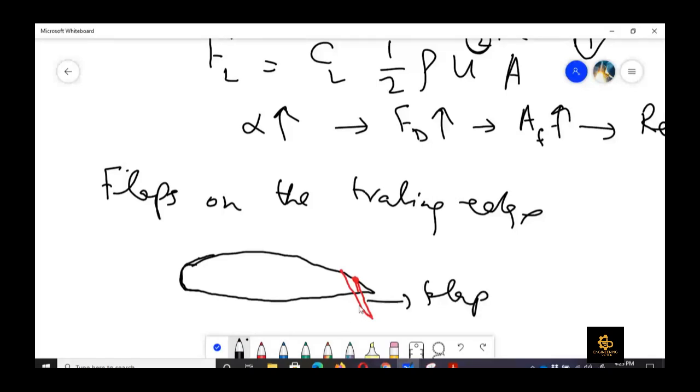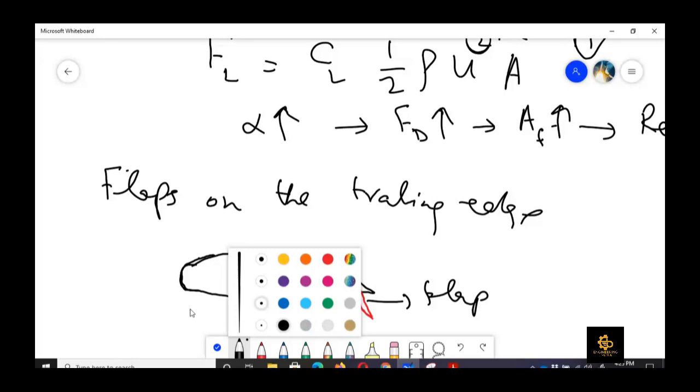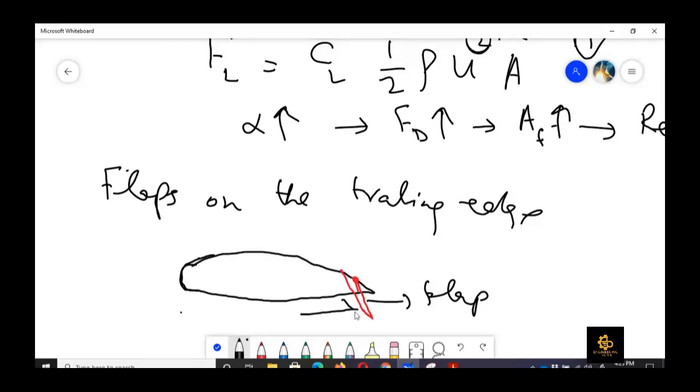When the flow is coming here, there would be higher pressure here as compared to this portion, so it would have higher lift. So it would increase CL. But the second consequence, because it is perpendicular to the flow, is that CD would also increase a little bit, depending on this frontal area, right? So CL would increase and CD would also increase. But the CL increase is more, because the CD increase can be overcome by putting in more fuel. If we can spend more fuel, lift would be generated more quickly in this case.